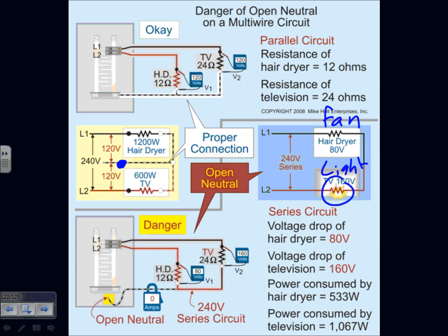So that's how dangerous it is. I can't emphasize this enough: if you are a wannabe electrician or you're an electrician, when you mess with the neutral, be very careful. Every time you see the neutral, it's more dangerous than the phase. The phase can give you a shock, and if you're careful, you'll be fine. If you open the neutral, you create fire, no question asked.